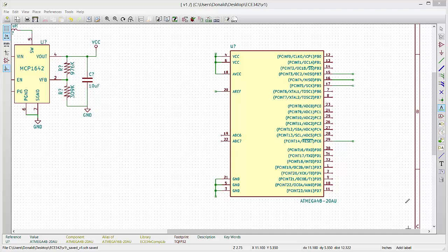Some people will suggest that instead you actually do everything in this fashion, where your connectors all have net names associated with them and your parts have net names associated with them, but there's no actual connections for any of them. I, on the other hand, like to, whenever reasonable, do the wired connection between things, because to the eye, the graphical flow and the flow of the circuit is much more obvious.